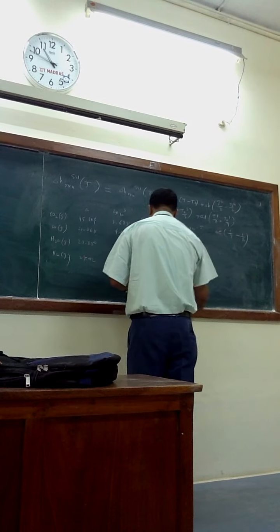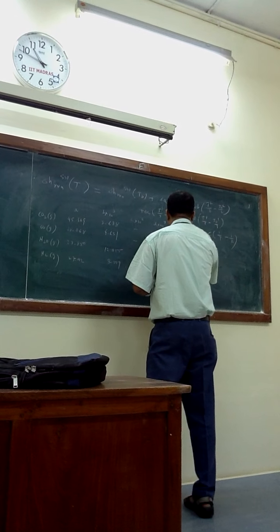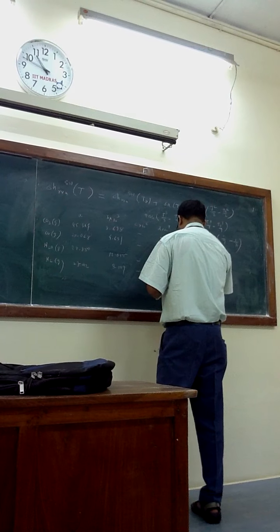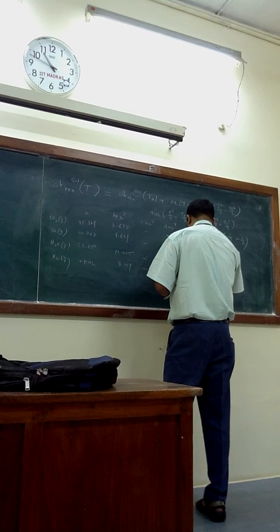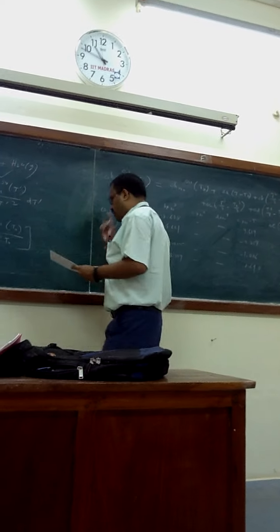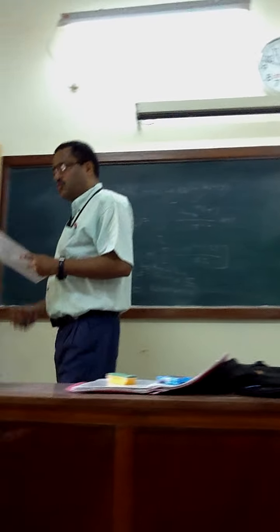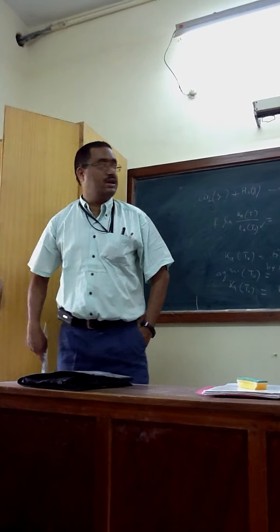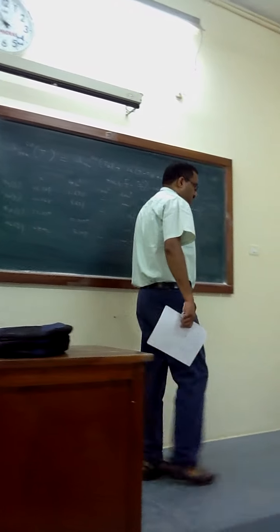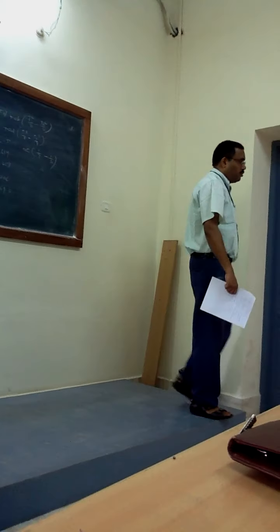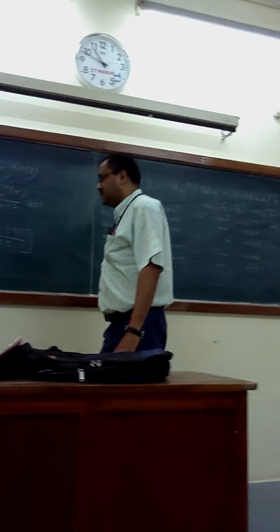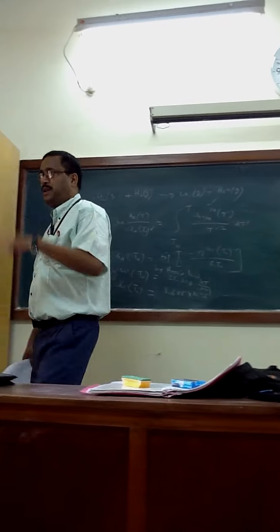No values are reported here. Minus 9.619, minus 0.258, minus 1.006, 0.690. The validity of temperature range is given as 2000 to 3000 degree Kelvin. When this Cp formula is given, the validity of temperature is also reported, and the reporting temperature range is 2000 to 3000 degree Kelvin. That means with that kind of variation you can happily apply this formula.